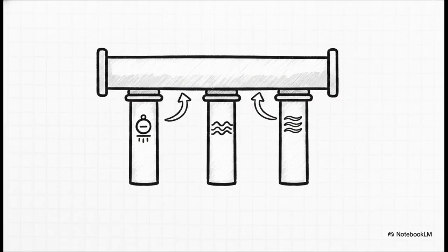So the crucial point here is that behind the scenes, these visual components are seamlessly exchanging information using fundamental continuity equations. Imagine our entire power plant as a series of control volumes. Everything is governed by just three main pillars. You've got mass balance, tracking enthalpy and pressure; momentum balance, calculating pressure losses and pipe friction; and energy balance, constantly monitoring the mass flow rates entering and leaving every single component.